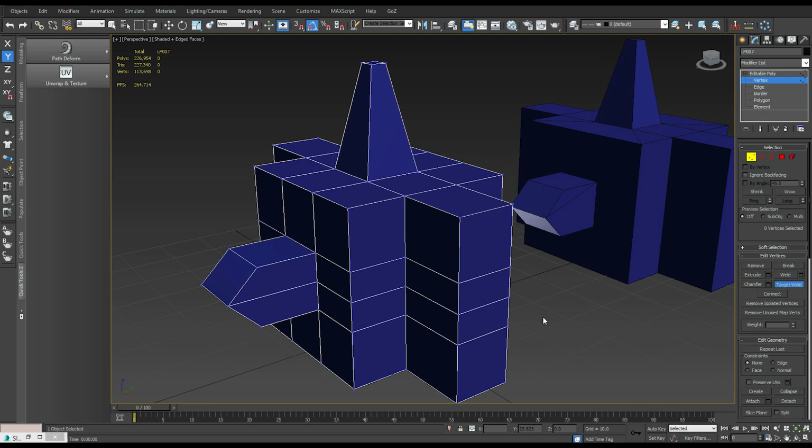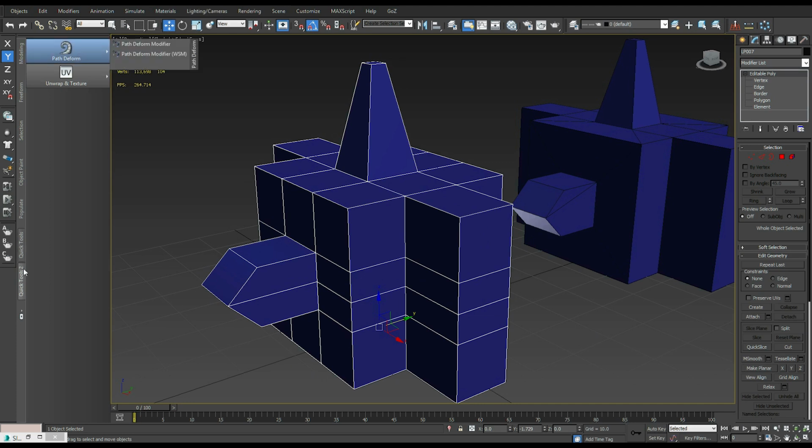There is another tool that in Max 2012 or later they came out with in the polygon modeling tools. I really haven't touched base on this. This is this tab here. It comes default right up top on the top of your screen, like when you just install and open Max. If you don't see anything at all, if you look right up here, make sure this is toggled on. It's basically a toggle ribbon. If that isn't lit up, it won't show up at all.